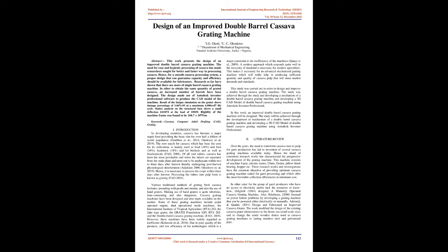Static analysis on the structural base shows a small deflection of 0.01074 at the load of 1094 N. Rigidity of the machine frame was found to be 104.7 times 10^6 N/m. Keywords: cassava, computer-aided drafting, CAD, grating.